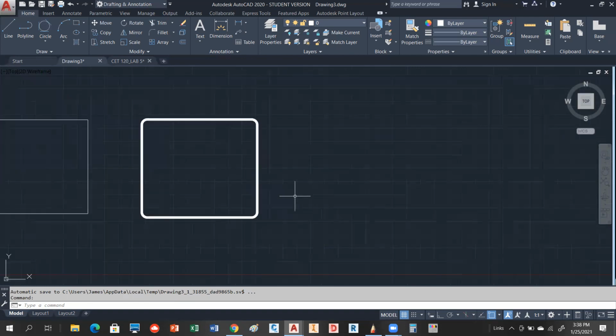Okay, one more thing to look at is what's called a chamfer. So a chamfer, instead of putting an arc at the corner, what it'll do is it'll put a straight line. It cuts it off with a corner edge. So instead of doing the arc, it's kind of doing what you might call a chord of that. So when I go to chamfer, what it's going to want to know is 2 distances. So you can come a distance down this way, and you can come a distance over this way, and they don't have to be the same distance. So those distances can be separate and different.